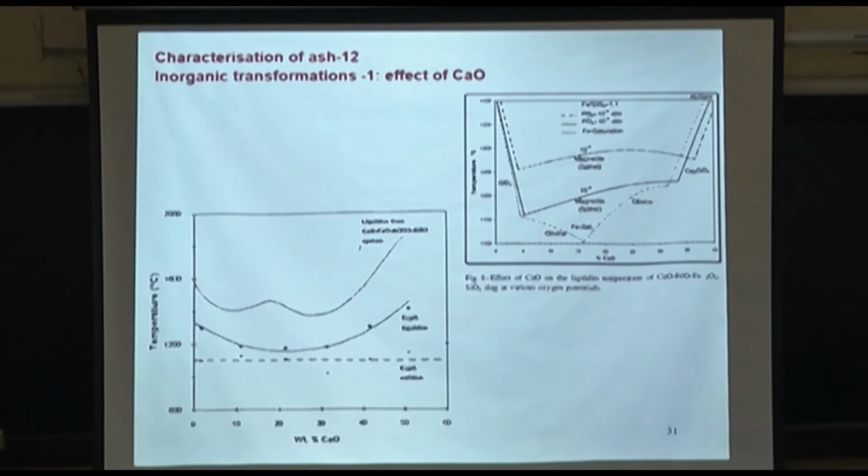In a fluidized bed, burning char particles' temperatures are easily 200 to 250 degrees centigrade higher than the gas temperatures indicated by the thermocouples. That is very well established. People have actually measured the particle temperature. You will see papers. One of my students worked on oxyfuel fluidized bed with large particles.